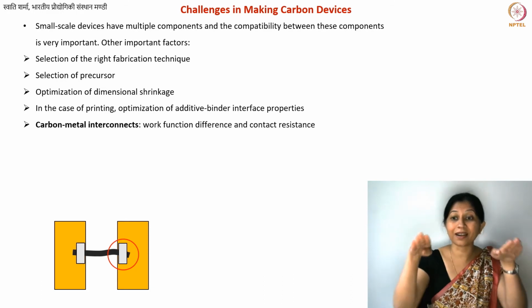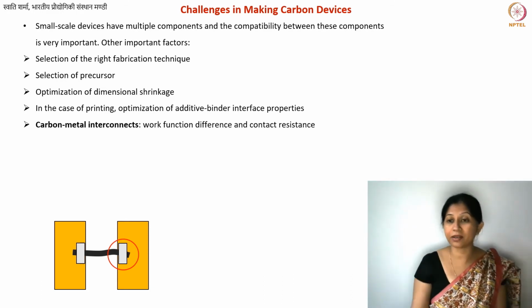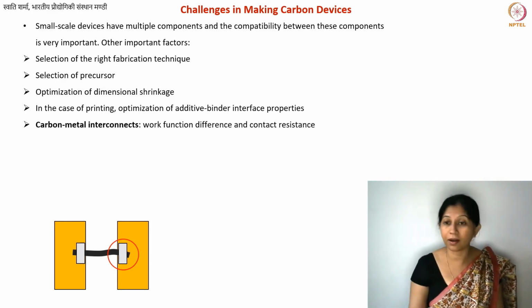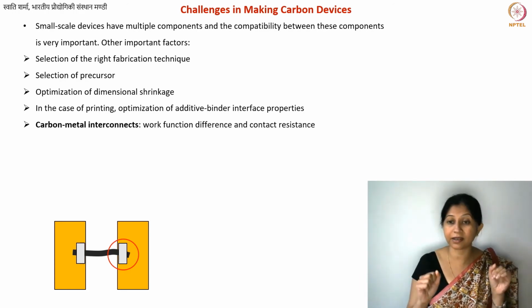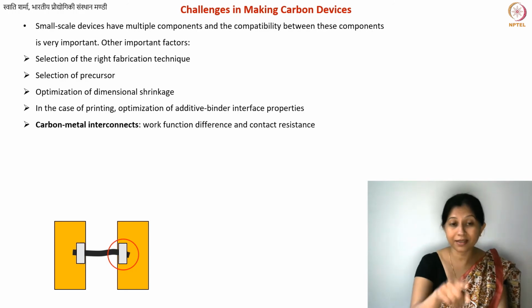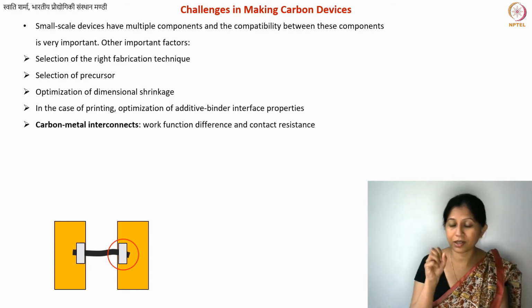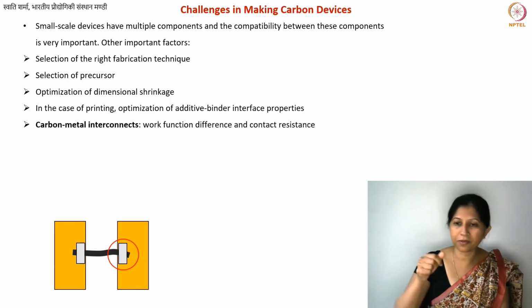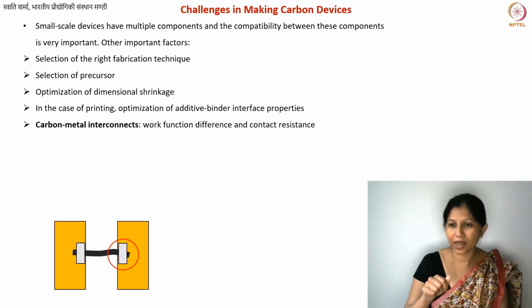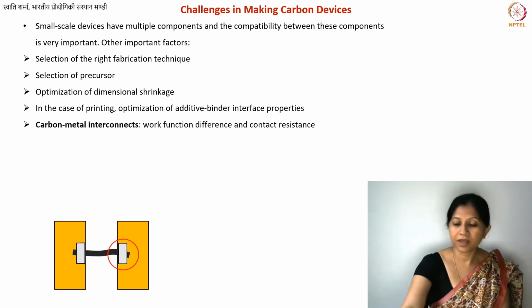But now I need some other sort of glue, and that glue could be another metal. It can be platinum. You can use ion beam deposition of this platinum. But something else, you need to hold your nanotube there. This is where I'm talking about the contact resistance, because now you have multiple of these structures, and at that scale you don't know if the adhesion is good or not. So this is what we are talking about.